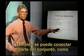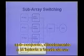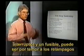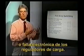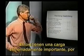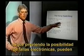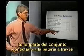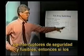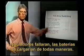We could also have a situation where part of the array, as a subarray, is connected directly through a switch and a fuse to the battery. The reason for this might be a concern for lightning considerations or electronic failure of your charge regulators. If you have an extremely important load and you're concerned that perhaps there might be electronic failures with your charge regulators, you could have a portion of your array connected directly through safety switches and fuses to your battery, so that if the regulators were to fail, there'd still be a part of the array trickle charging your battery.